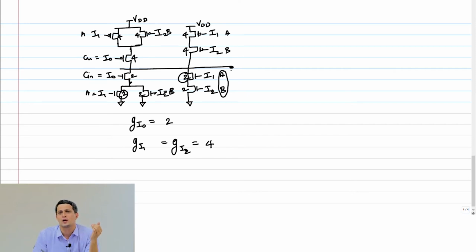This stack would have taken over and settled out to 0 already. If G was 1 for that kth stage, then that carry out would have already got set by this parallel stack here. Right? So we have also accounted for the fact that the signal coming last is connected to the transistor that is closest to the output, thereby having to discharge least number of capacitors in the circuit.